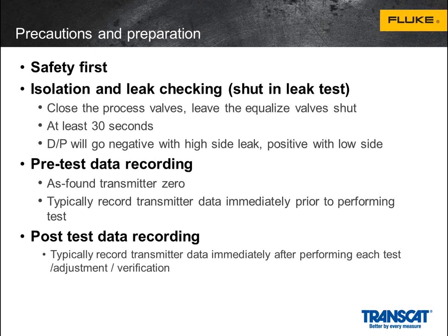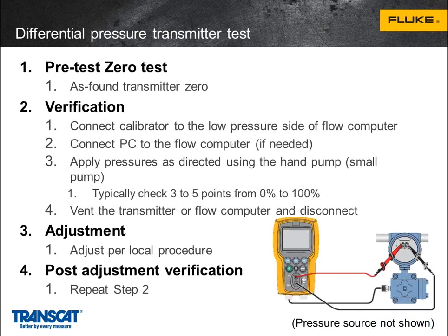Two, the technician doesn't have to write the data down, which makes his life easier and means there are no errors in recording. That can then be documented with tracking software, which feeds back into the main purpose of this, which is to maintain accurate calibration records in case of a dispute. Your records can protect you from being accused of manipulating your transmitter.